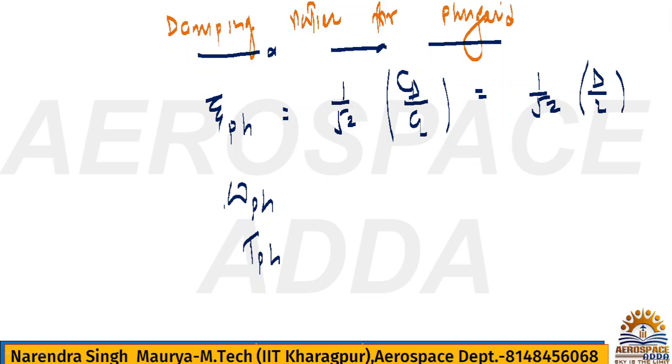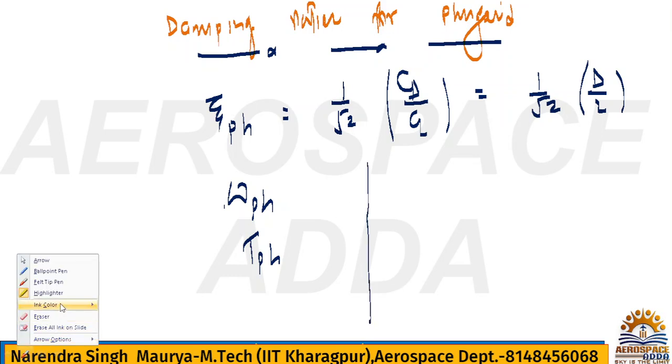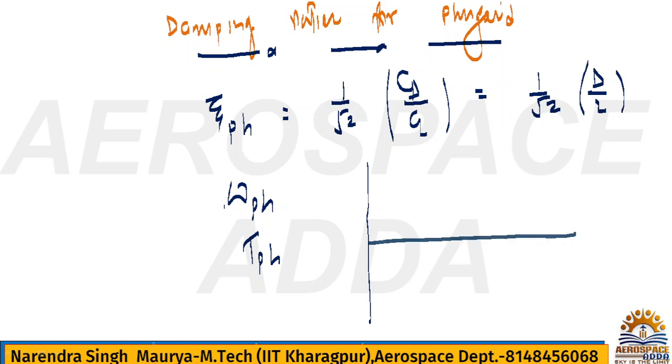All right. So if drag is more and more, then the damping ratio will be more and more, and that's the reason. You can connect it with the theory also. Damping ratio means what? I explained damping ratio or damping. What is damping basically? Suppose oscillation has started. Once a disturbance hits the airplane, the airplane will start oscillating like this.